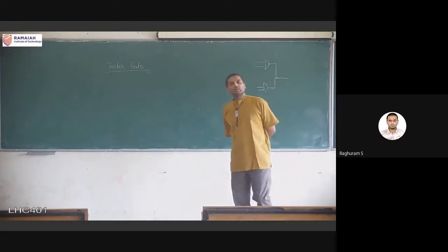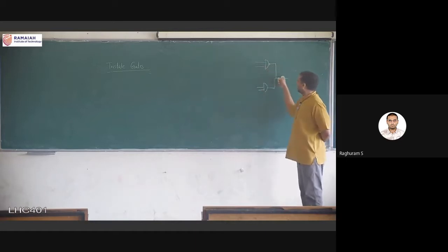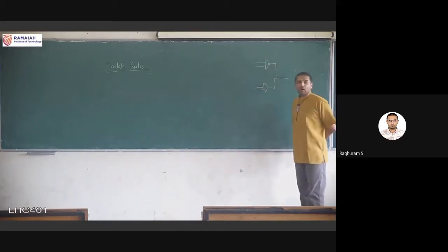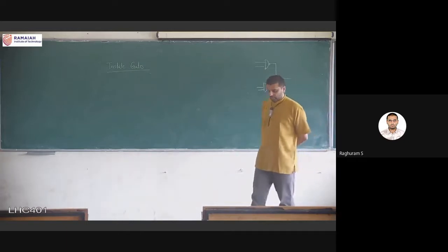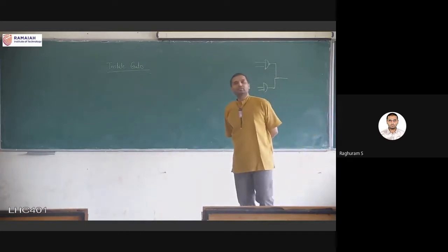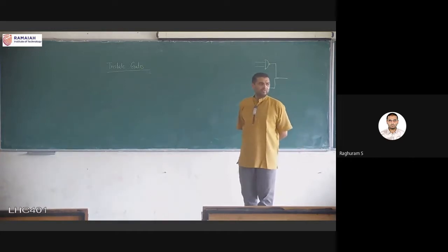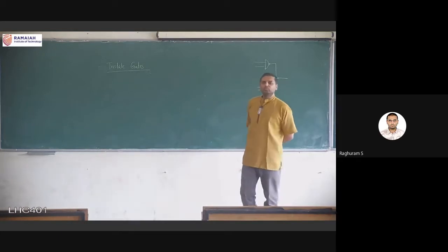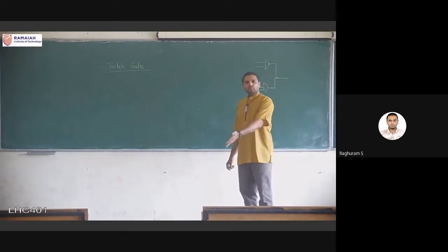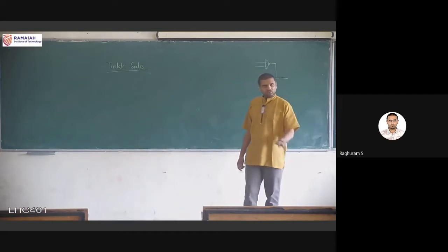Why will you not see this type of connection anywhere? I'm having a NAND gate and an AND gate, with the outputs of both connected to each other. There are 2 reasons. One is, if the outputs of both are the same, there is no reason for 2 gates. You just use the output of one of the gates and completely eliminate the other gate.